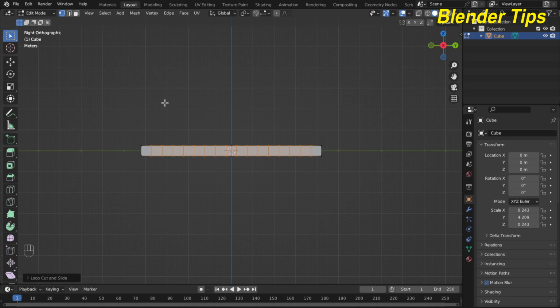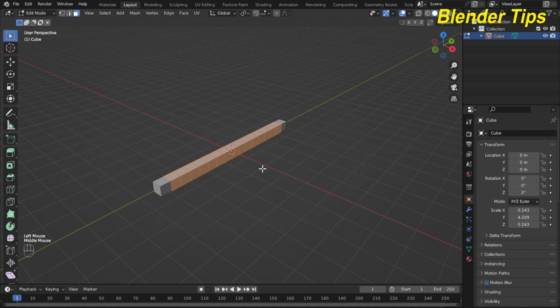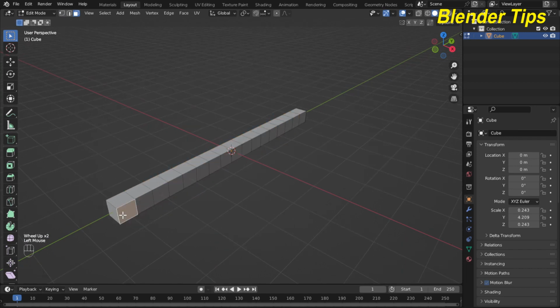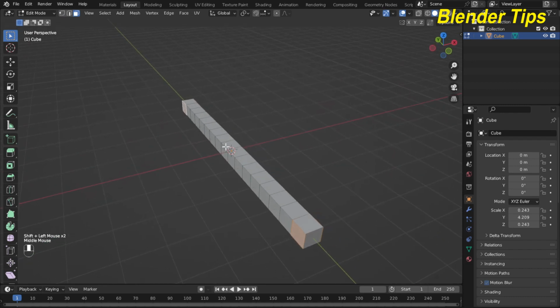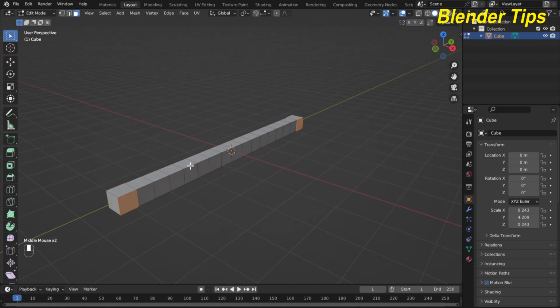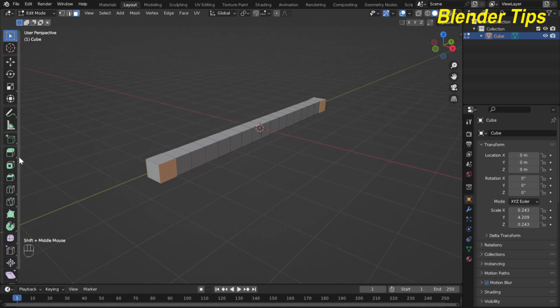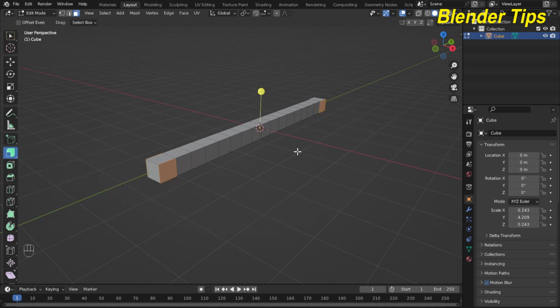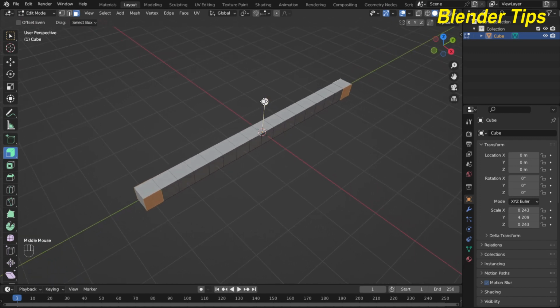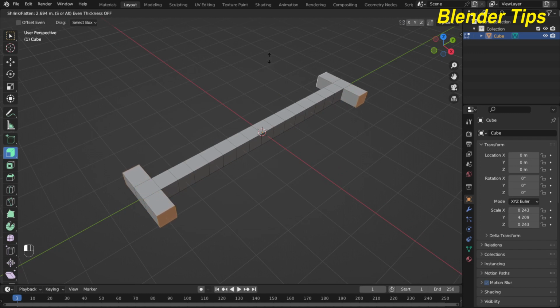something like here. And now face selection mode, and now I select these faces by pressing Shift. Nice. And I extrude these faces along normal. So for that, here I select extrude along normal, and here I drag this option something like this.